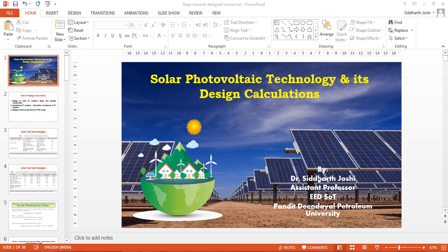module and its connection. Suppose I need to install 1 kilowatt of rooftop power plant, then what should be the connection? One can connect two modules of 250 watt each in series, and the other two modules of 250 watt each in series, and both the strings, comprising two modules each, in parallel. Or one can go with 4 series connected modules or 4 parallel connected modules.